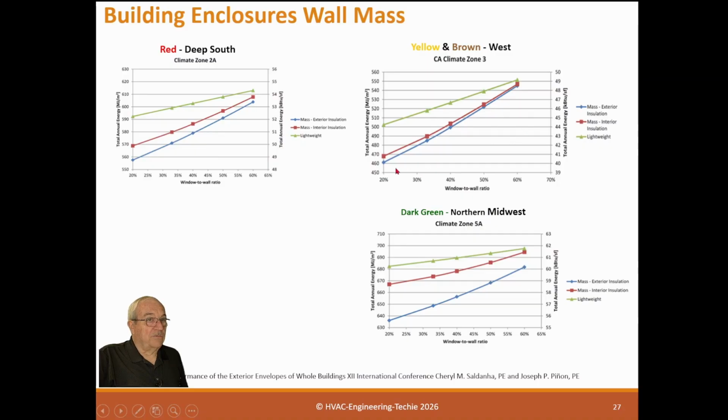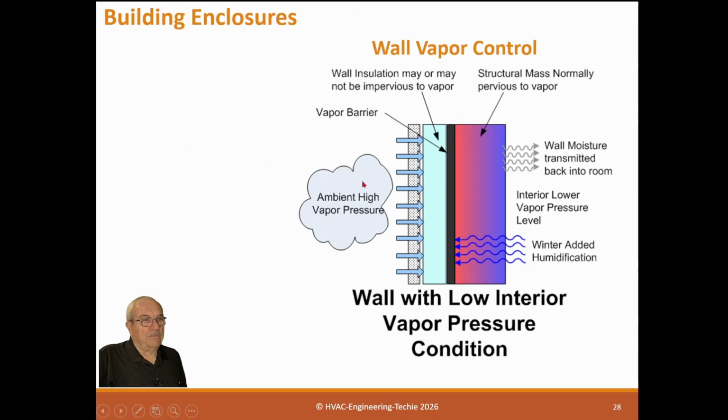Of course, this is where I live. So it says it's not much, but it's still better. It's always better. So I preached that for many, many years, that it's best to build a mass wall. And especially if you're pressure testing a building, a mass wall building works much better than a frame wall. So if you're trying to get down to 0.10 leakage rate, I hope it's a mass building, because it's going to be hard getting it there otherwise. So this is really good information to have, to know that these mass walls are important if the building really wants to be sustainable.